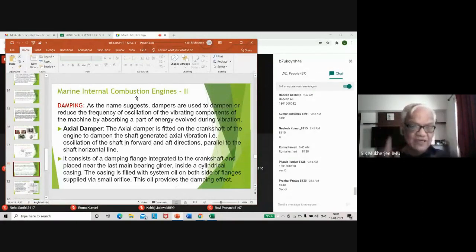Thereafter, when you get the chance and time, space, and the material, you arrange to repair that pipe. You may have to stop the oil from there, take out that pipe, do a little welding, then reheating to reduce the stresses that are developed, and then put it back in place with a cushion and tighten the clamp and make sure it does not vibrate again. Or you may need to crop that pipe if it has been worn out after repeated hitting and it cannot be welded. You need to crop that pipe, put an insert, weld the whole thing around, and then put it back in place. So these are measures you will need to take and be very, very resourceful.